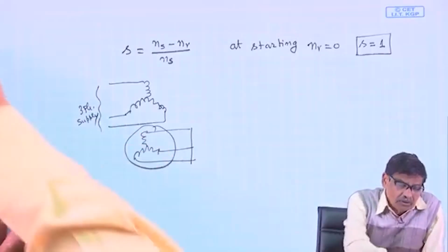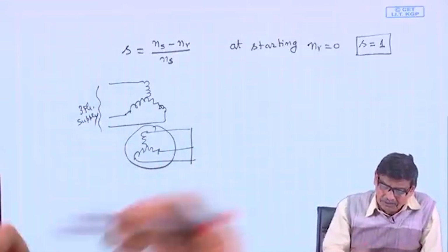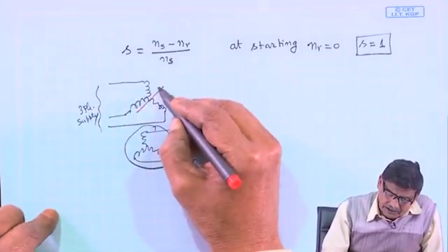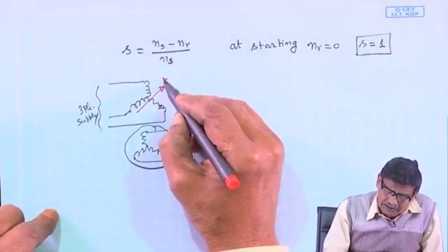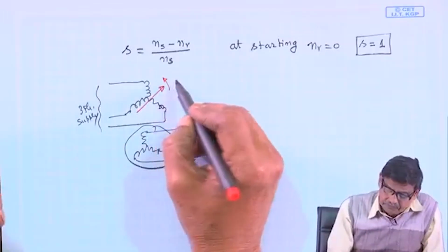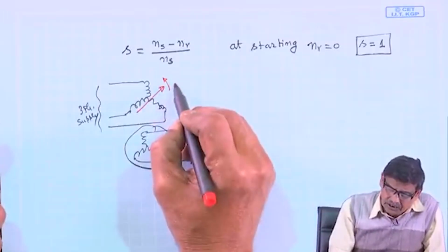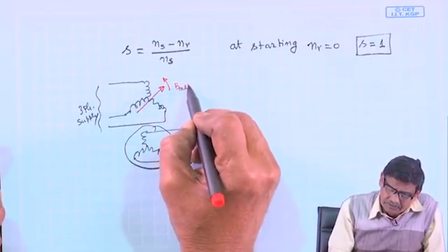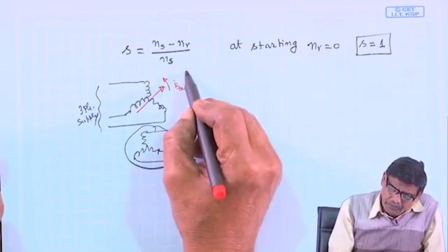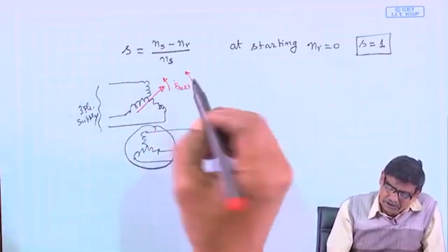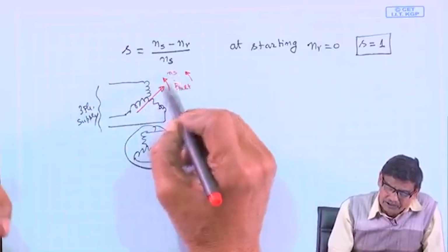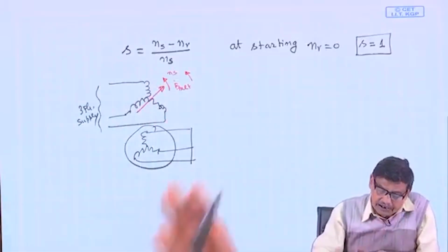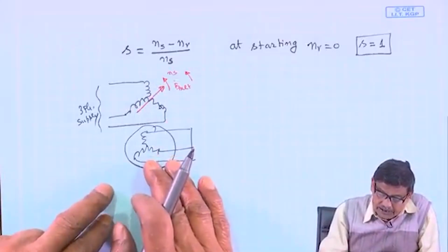and I know with proper phase sequence, with rotor closed, ultimately it is B net, or Bs, which is moving with synchronous speed Ns with respect to a stationary observer, and rotor is yet to start.